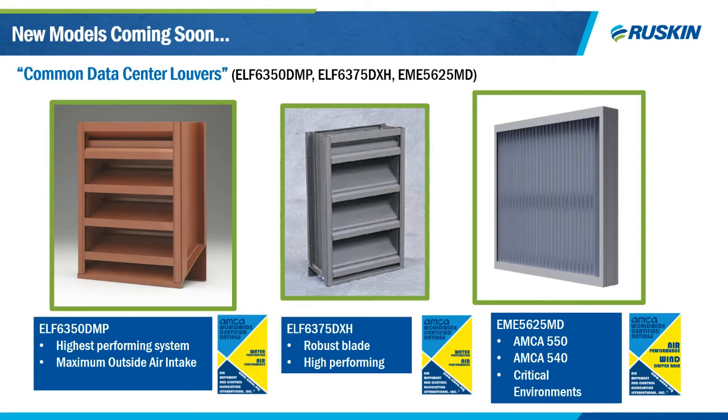That MD does stand for Miami-Dade. So this is a vertical blade Miami-Dade rated louver that is designed specifically for keeping airborne debris out of your building. And this is not just for Miami, it's not just for Florida. This type of louver is ideal for installations where it's critical that the servers remain operational during a storm event.